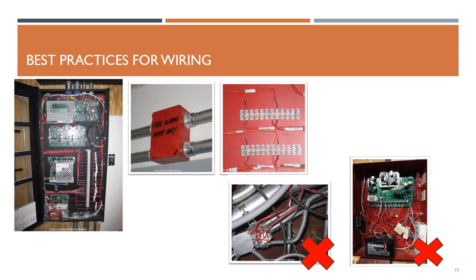The code does not specify the use of splicers, but as an installer experienced in the installation of fire alarm systems, we advise that you use this splicer for boxes, power supplies, or fire alarm panels where there will be several connections. In this way, you can avoid what happened in the picture below.